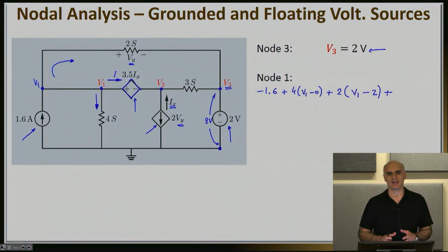Now the trouble here is that we really don't have an equation to express this current. I can't use Ohm's law for a dependent voltage source. It's not a current source where I could immediately know how much the current is. In reality, as we have discussed several times in the past, there is no way to know how much current flows through an ideal voltage source.